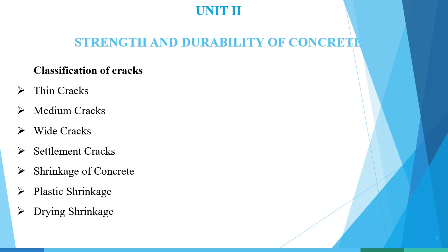The next one, shrinkage of concrete. Shrinkage of concrete is one of the important factors contributing to lack of durability of concrete. Shrinkage is mainly responsible for causing cracks of large magnitude or minor microcracks. The aspect of cracking in concrete is very complex, involving many factors such as the magnitude of shrinkage.